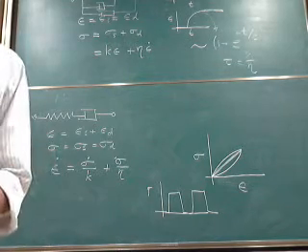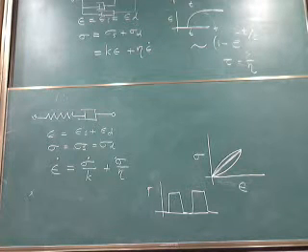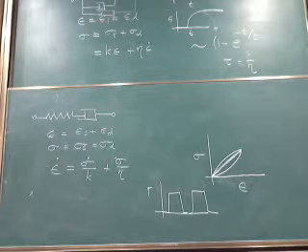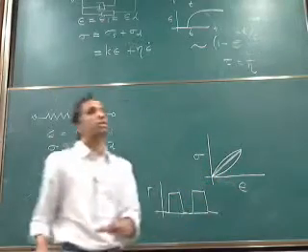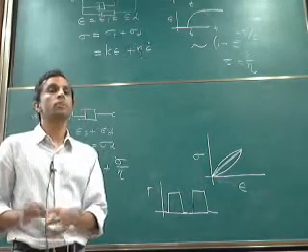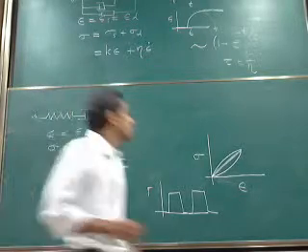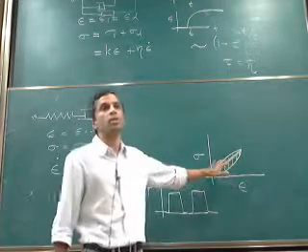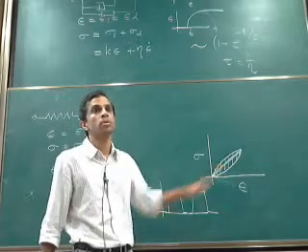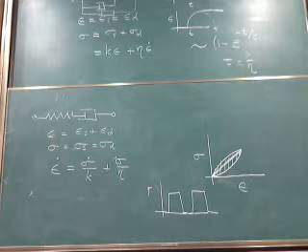There is dissipation. In fact, any material you take, if you take water, again, like I said about Mount Everest, water can behave like a solid at very short times. But at long times, it's a liquid. So, any material you take, if you look very carefully, you will see that there is some dissipation, any real material. Okay, so the ideal elasticity is in most cases an idealization. So the area under this curve gives you the energy which is dissipated, okay, in each loop. So this is one way to test whether it's an ideal elastic material or a viscoelastic material.